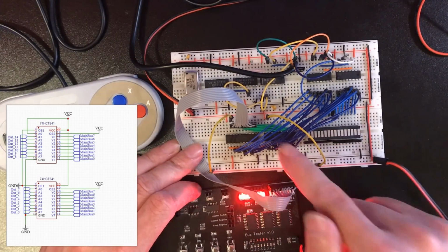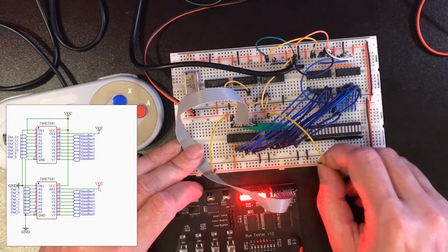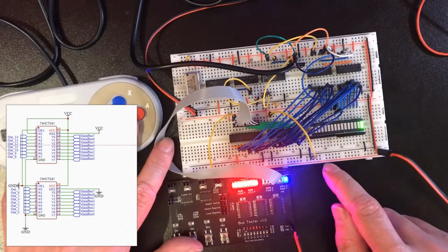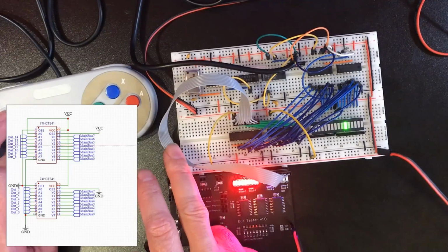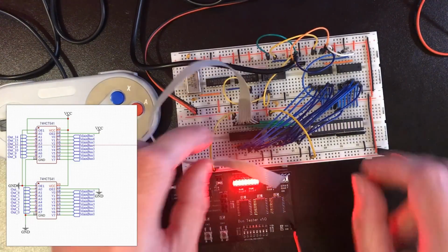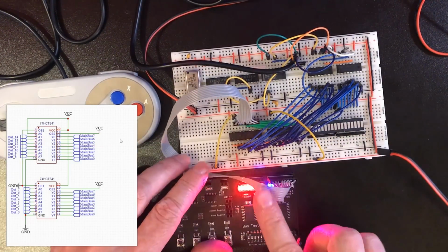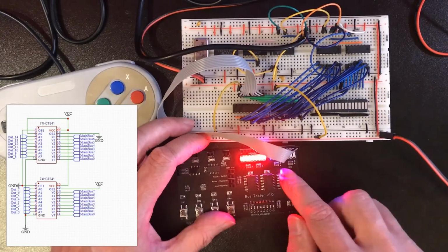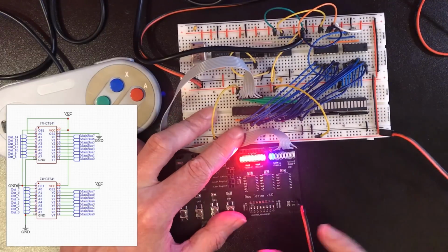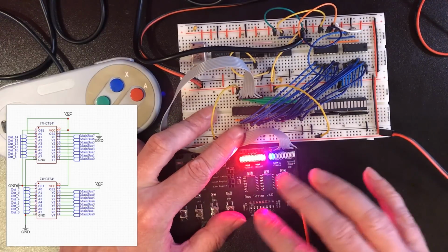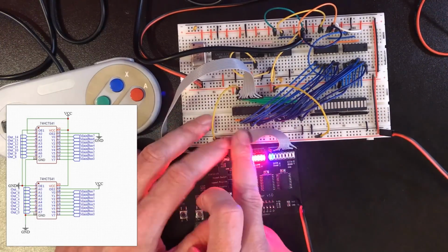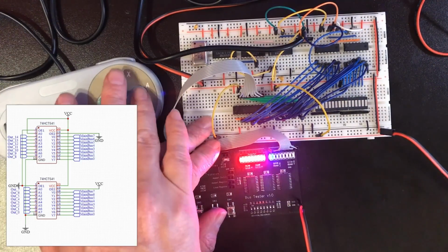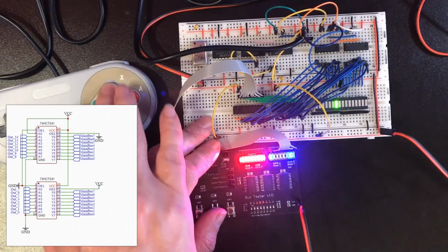Okay, so if I take the active low for this one low, then that line driver is driving the lower 8 bits onto the bus. That's cool. We turn that to high, and now I take the active low for this line driver, put that low, and now that top bit is permanently on, and that's the signal we're going to use to determine which of the 2 registers we've pulled in. Now all of these buttons don't have an effect, but the new ones do.